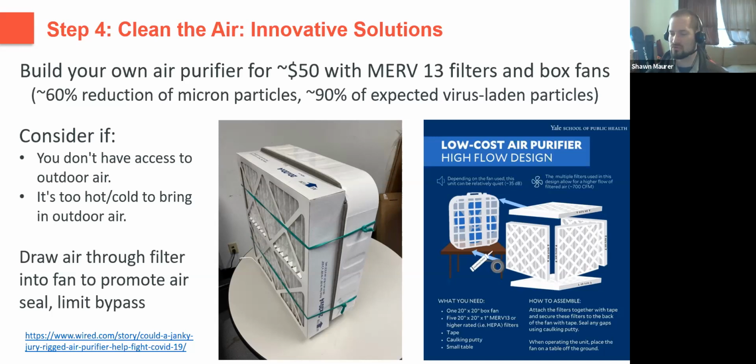If it's too hot or too cold to increase outdoor air ventilation rates, or if your system was unable to be upgraded to a MERV 8 or a MERV 13 system due to airflow issues, this is a good, cheap way to then increase that filtration rate within the space itself.